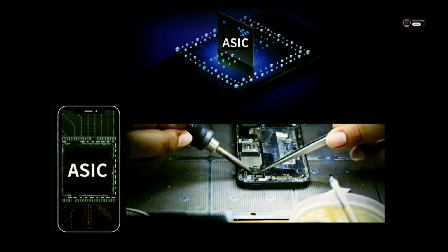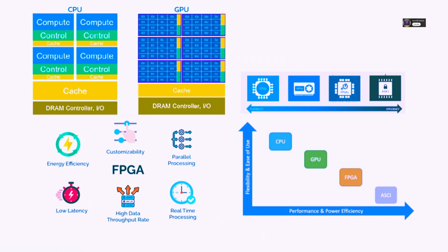The sources really hit on this. ASICs are basically mandatory there, not just for cost, but to stay within the thermal limits and maximize battery life. Exactly. You need that absolute best power-to-performance ratio. You just can't afford to put a relatively large, power-hungry FPGA in a tiny, battery-powered handheld device if an ASIC alternative exists. That's why phones have dedicated ASICs for things like the camera's image signal processor, ISP, or specialized AI neural engines. They do those fixed tasks with incredible precision and minimal power draw.